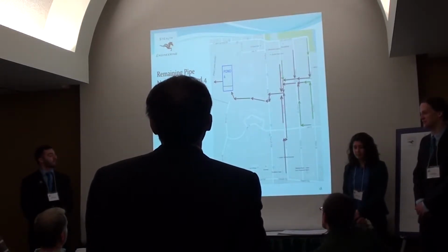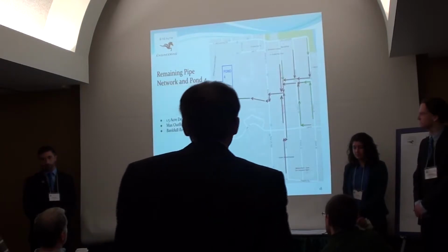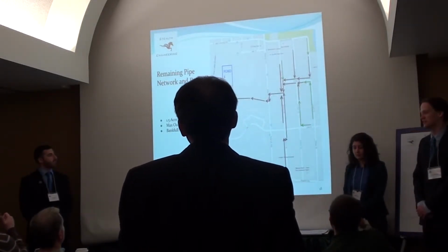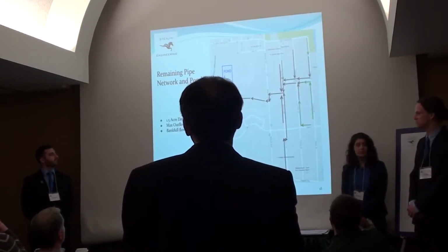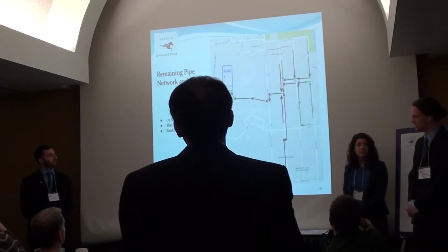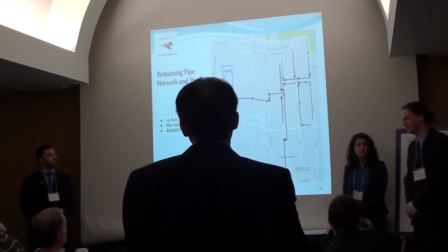For the 35 acres of land, the max outflow based on the regulations is 5.2 CFS, and the outflow from this pond using the pulse method is 4.9, which meets regulations. We then did the bankfull again for this pond, and it took 36 hours, which again meets regulations.